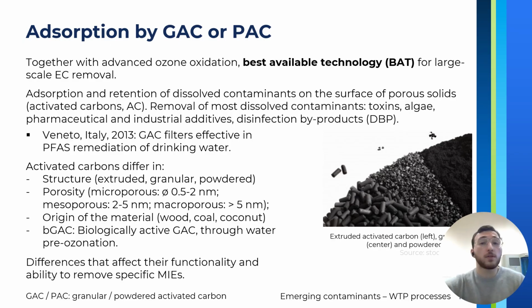Activated carbons are prepared from a carbon source, which may be wood, coal, or coconut shells, through an activation process, which increases the surface area of the product and thus its ability to absorb and retain contaminants. By adsorption by activated carbon, removal of a wide range of dissolved contaminants may be achieved, including toxins, algae, pharmaceuticals, and industrial additives, as well as disinfection byproducts.